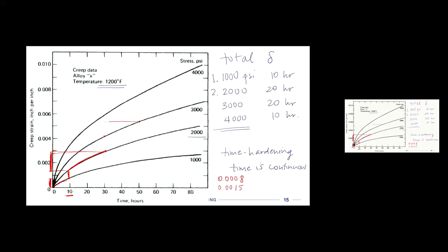And so then we come across, right? We sort of calculate our third increment of creep strain here. And I think I came up with slightly larger than those tick marks. So I had 0.0011, right? Approximately 0.001. And then we do the same thing for the fourth one, but now we're only 10 hours.